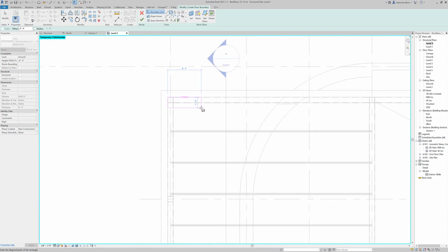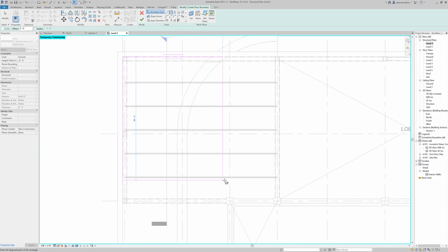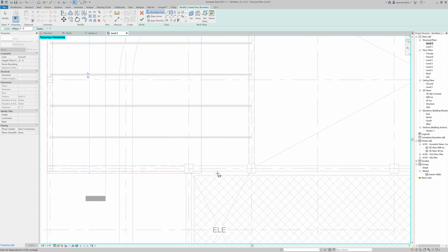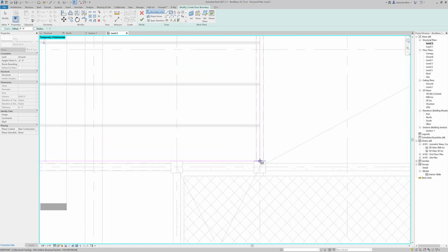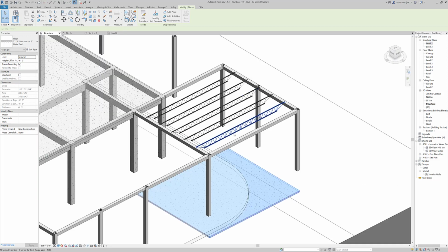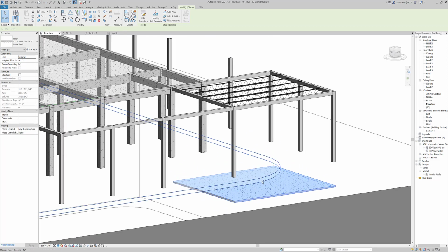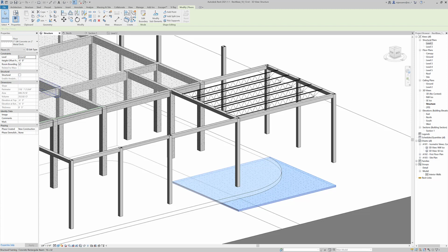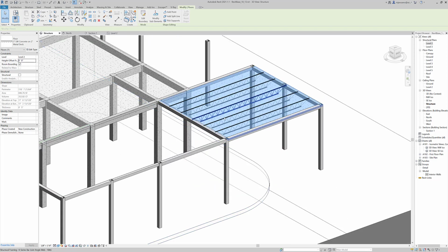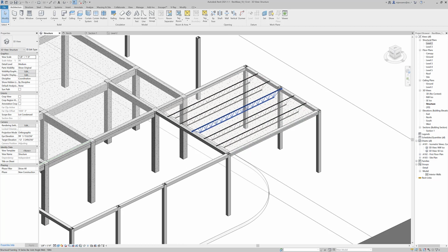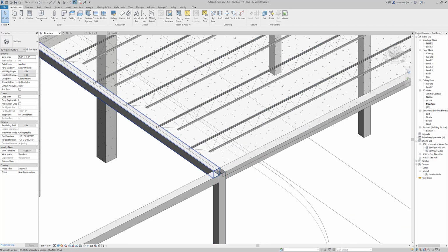And there are different ways to do this, and again, this class is not necessarily going into those sorts of details, but I'm just using the perimeter of my structural system, and I'm going up to the perimeter of my concrete system. So here I'm going to hit check, and now you can go back to the 3D structure, and you can see that I placed that on the wrong floor. The easiest way to do this is to go to the parameters and make sure this is on level 2. And it has a 0 height offset, and you can see it'll jump up to the top there.